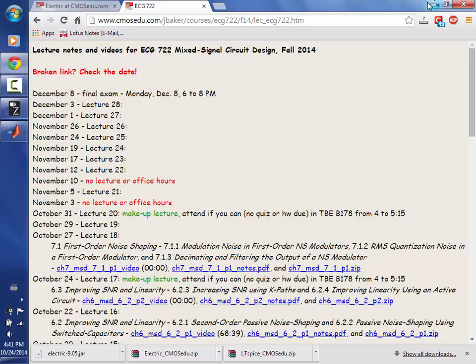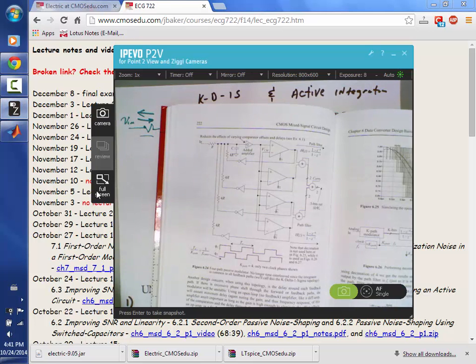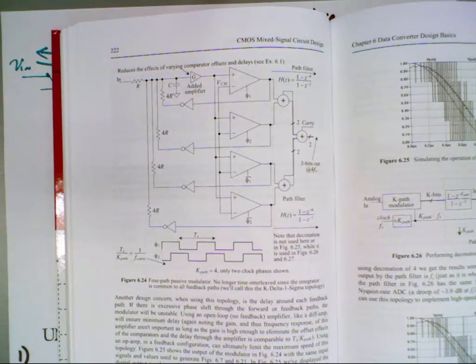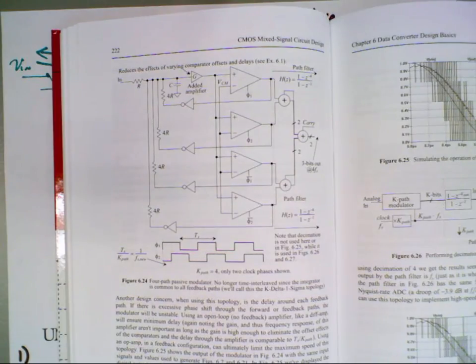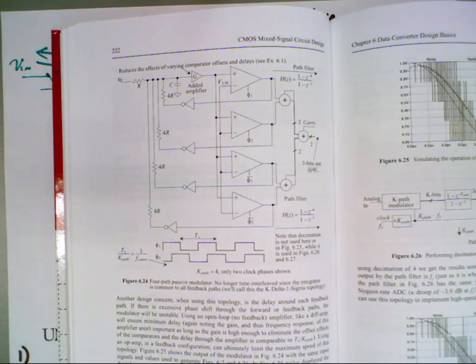So, do we need to talk about the K delta stuff anymore? Let me just go through some basic questions and make sure everybody's on board. So, first question I was asked right before, why is it 4R versus R? Yeah, so the gains are the same. So the effective feedback signals the 4Rs in parallel, and there's 4 of them, so 4Rs in parallel are R.